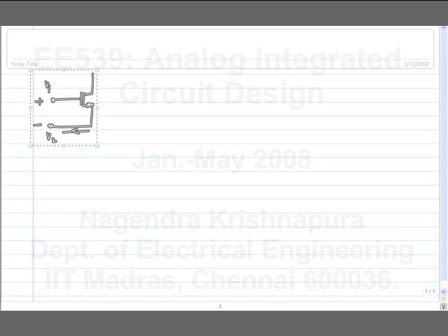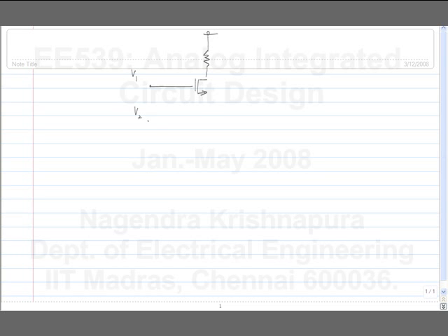So some kind of heuristic reasoning gave us this. We do have already a transistor amplifier which amplifies the difference between V1 and V2. The only disadvantage of this is that V2 sees a very low impedance input.